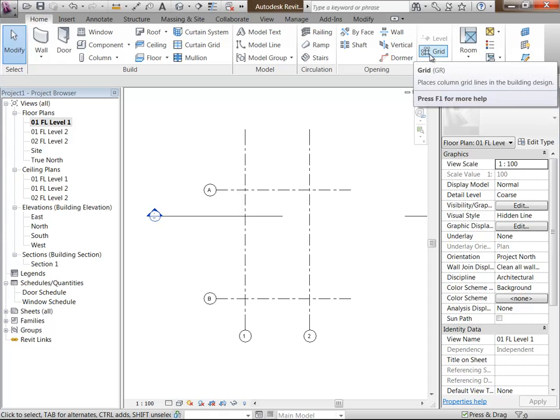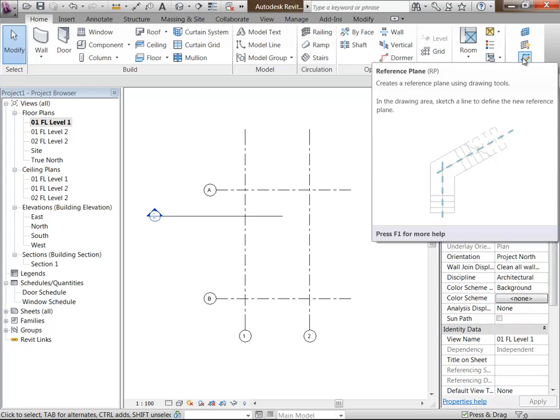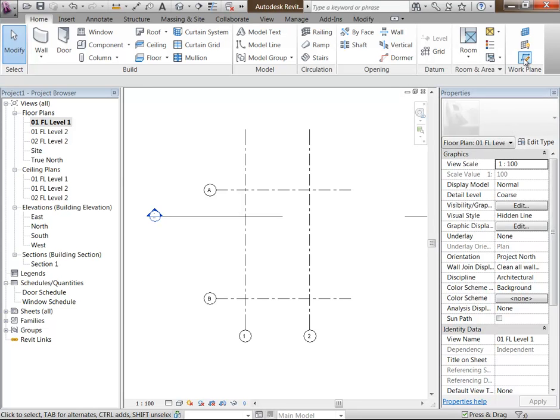Are these reference planes totally accurate? I mean, you're doing them by eye, and so it's relying on the showing that it's 90 degrees. Yeah, the angle is 100% accurate. The length of them is never accurate. Well, you can measure it, but the length isn't really important because it's just a graphical symbol. But the distance between them is always 100% accurate. So yep, they are totally accurate. They set the location for everything else, so they've got to be spot on.